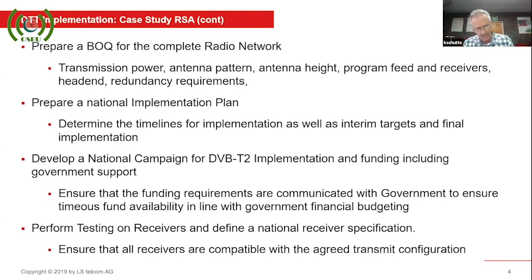If we use a tool to do that, I will just look at the combined field strength. If I just want to look at interference, I will go for 1% of the time. So I will look for the unwanted or the interference calculation, and you can then produce it over the whole area with the actual transmitted levels.